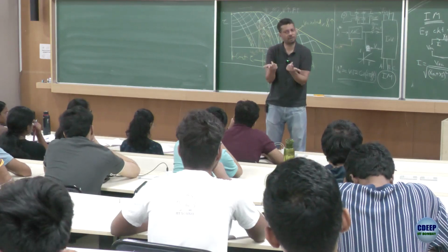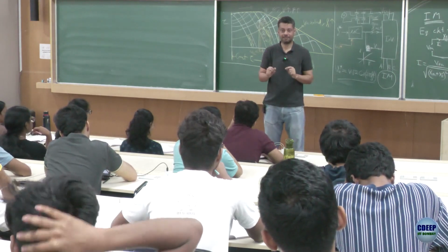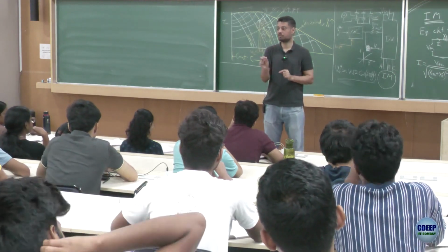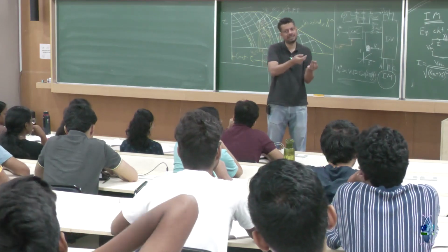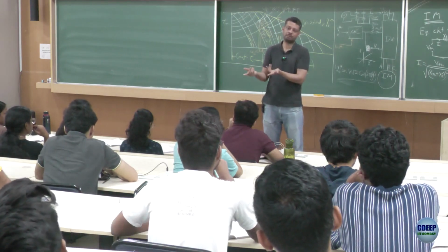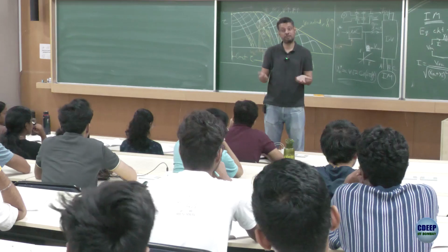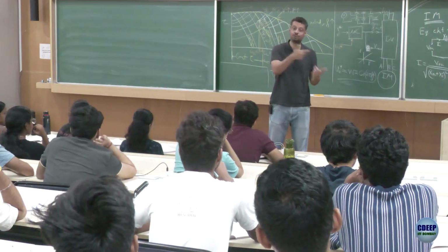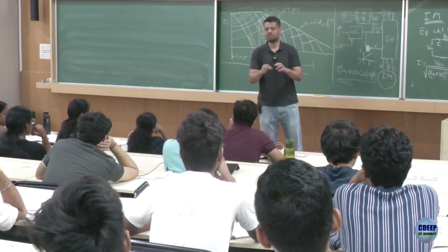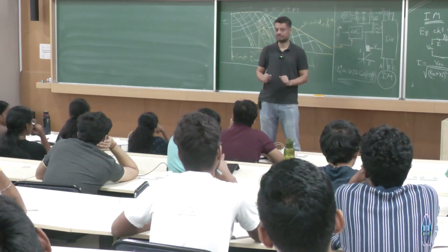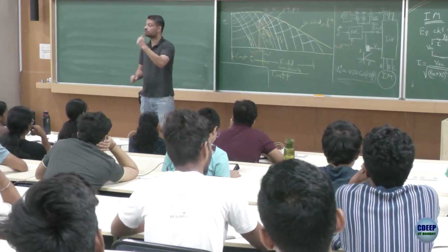So this is anyway an electronic signal. For our convenience, we put a display, and on that display it comes out as 2000 RPM. But actually it's an electronic signal. So why can't you take that electronic signal and supply it to a microcontroller, which will have an analog to digital converter anyway? It would have GPIOs also. The counting mechanism also you can do in the microcontroller if you want. So measuring the speed using an electronic circuit is not that challenging. What was her question? How do you know how much to increase, right?